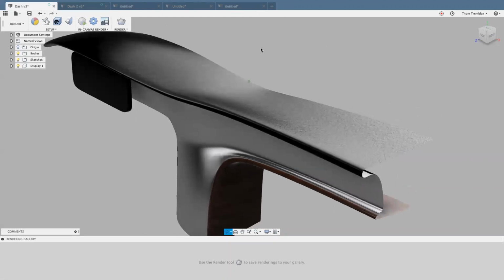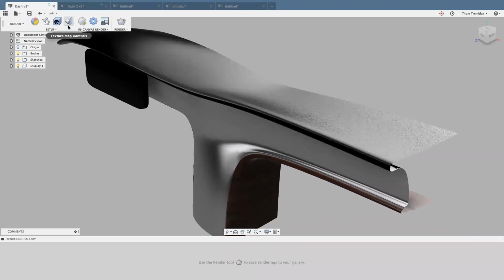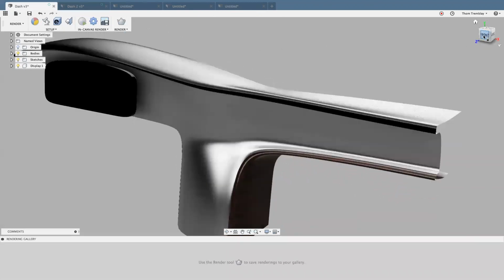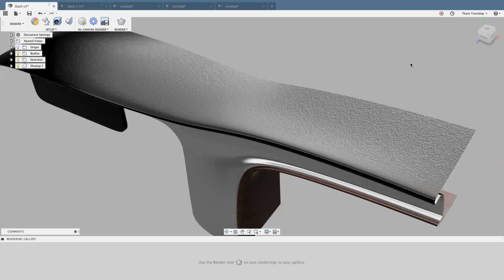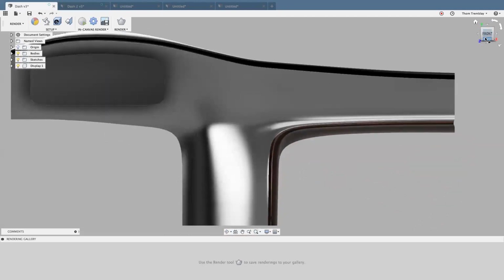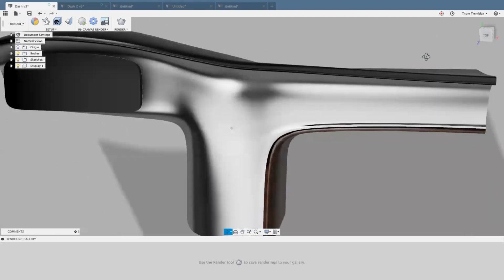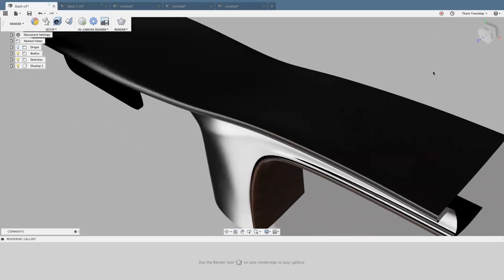So let's talk a little bit about environment and your overall lighting. One thing that can cause frustration or problems is, let's take a look at how this model looks right now. It's going to pop back here in a second. So I can kind of see the texture, it's highlighted. However, this is a really common problem. If I were to make this the top instead of the front, it can obscure how that texture looks. Because we're using environmental lighting, if the orientation of your environment isn't correct, it will give you problems. However, sometimes you can always reorient in order to create better lighting too.